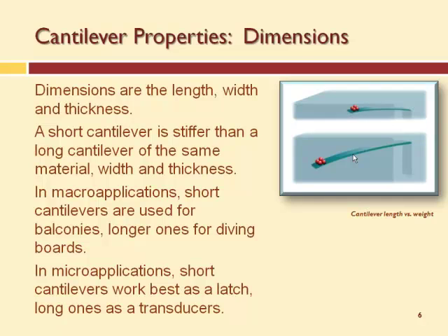What they're trying to do is adjust the stiffness to what kind of dive they want to do and how much they weigh and that sort of thing. So you can change the length of the diving board or the cantilever to change how stiff it is. Okay? So short cantilevers are used like in balconies. Longer ones are used in diving boards. They have diving platforms, which are very short cantilevers and made out of concrete. So there's no spring to it at all.